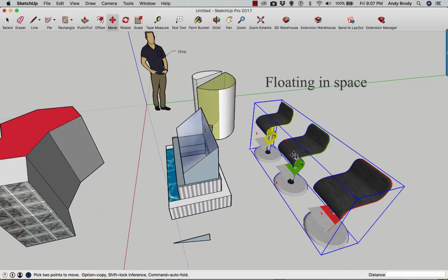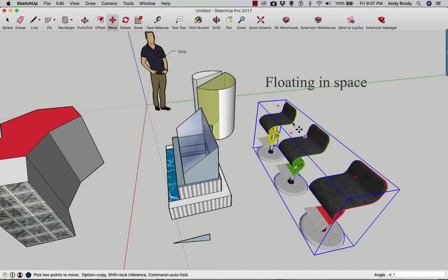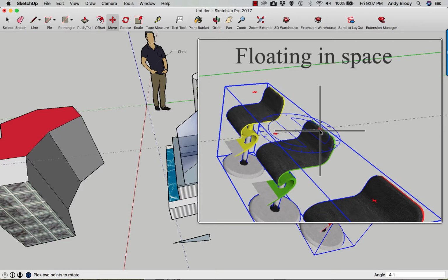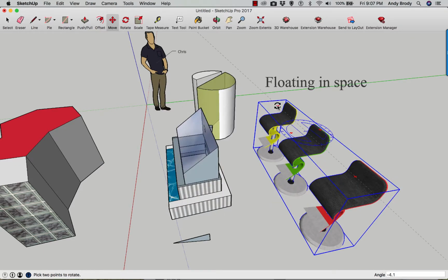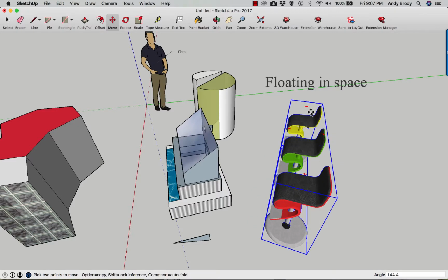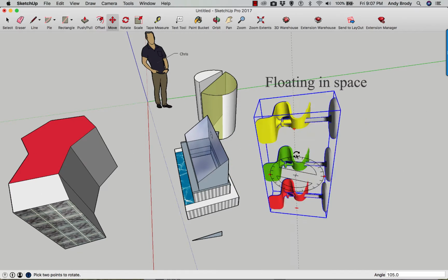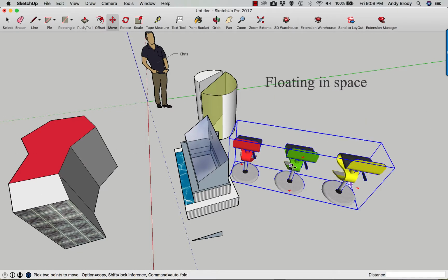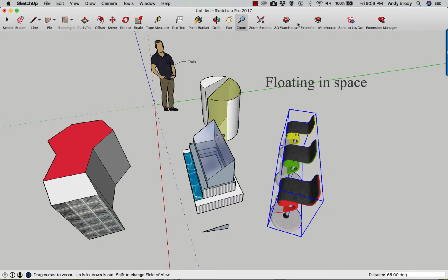In fact, when you use these objects, one thing to note is that the move command works particularly well with what are called components, which in this case is what you get off the 3D Warehouse. As I move my mouse over that component, you see these grips that show up, like little red pluses on the different corners. Those allow you to rotate the object, and you can even rotate it based on some number if you so desire. You can even rotate it up into 3D space, which is a little funky, but maybe that works with your design concept. Anyway, the 3D Warehouse is very handy.